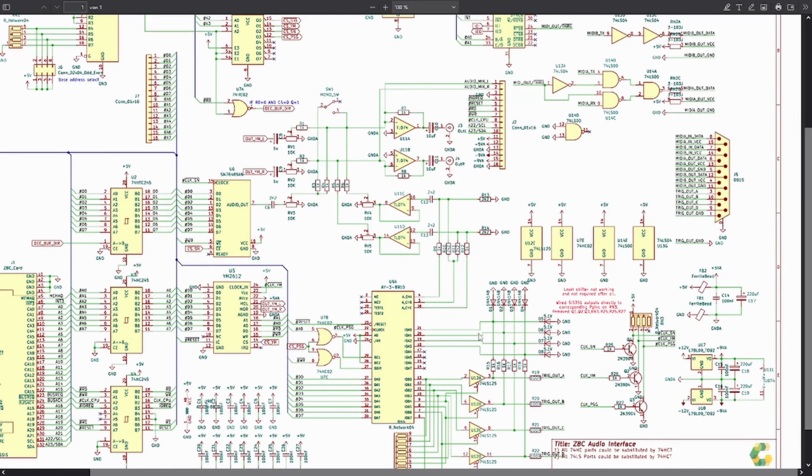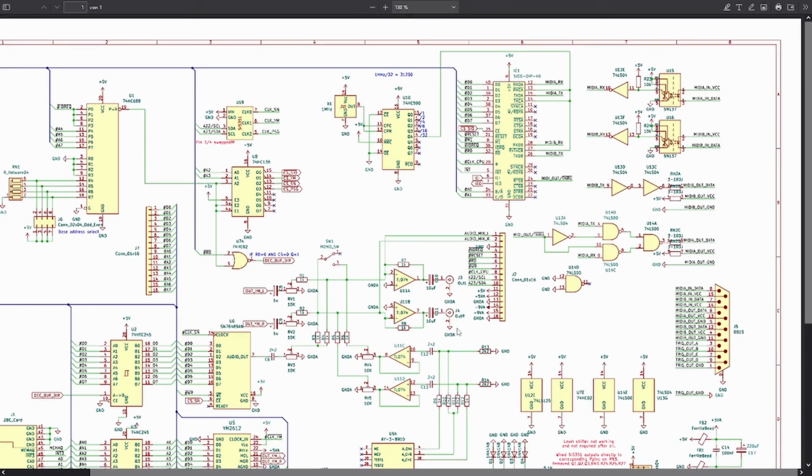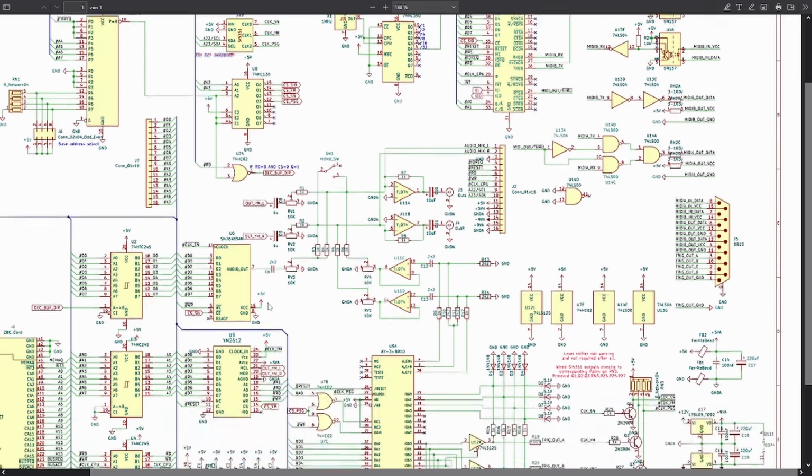The only 2 things that are left is the clock generation for the sound chips, which is, as already mentioned, this SI5351 right here, which then provides the clock signals to those 3 ICs. As you can already see, there's a mistake which we have to fix in this video, and this is that pin 3 and pin 4 are swapped in this revision.